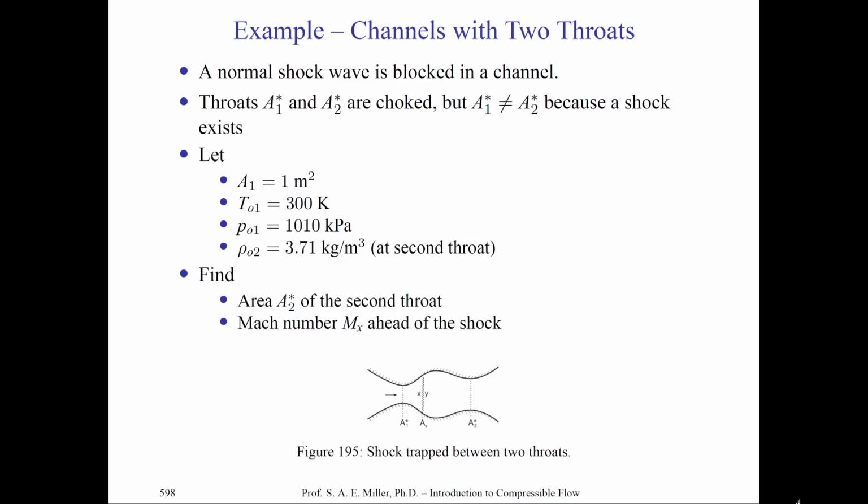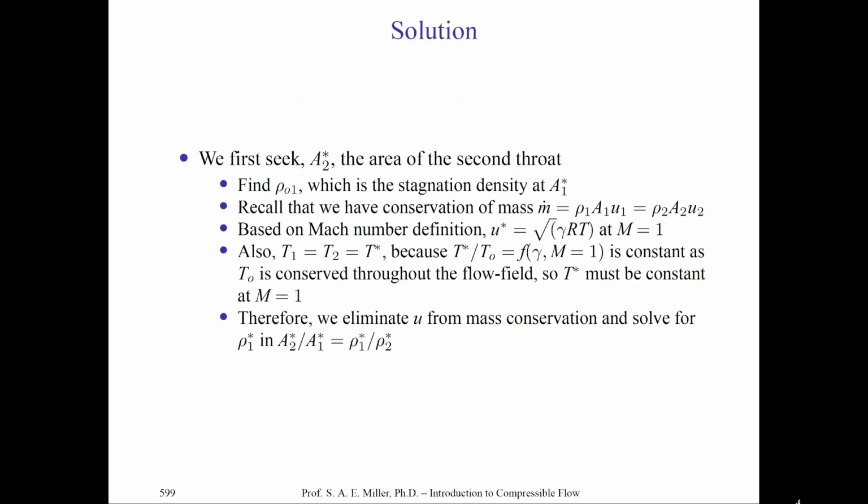In this situation, I would like us to find the area of the second throat, which is choked, and the Mach number Mx ahead of the shock. Let's begin. We first seek a particular solution, A2 star, the area of the second throat.